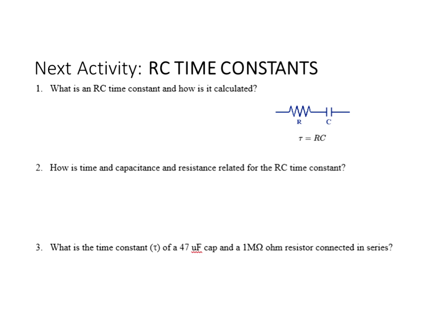Okay, what is the time constant for a 47 microfarad and a 1 megaohm? Well, all you do is you multiply 47 microfarad, 47 EE negative 6, times 1 megaohm, 1 EE6, and I get 47 seconds. So 47 microfarad times 1 megaohm gives me 47 seconds. What you see on your calculator is 47 seconds.